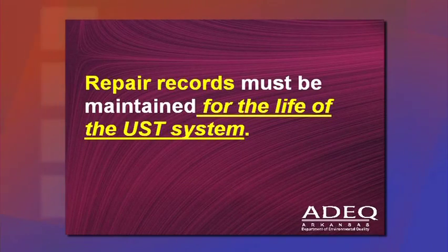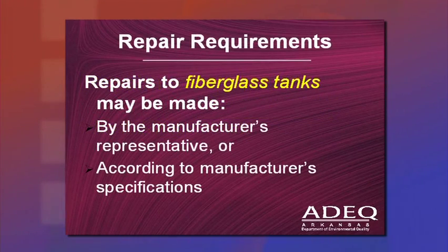Any repair records must be maintained for the life of your UST system. Any repairs can be made to fiberglass tanks if they're done by the manufacturer's rep or according to the manufacturer's specs.